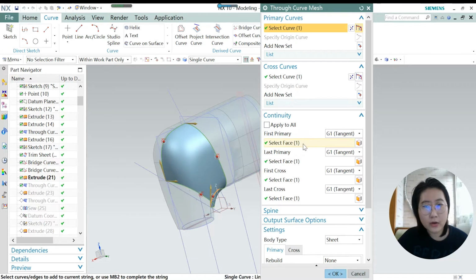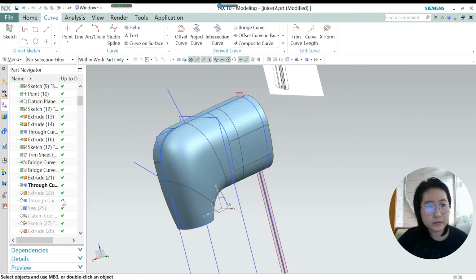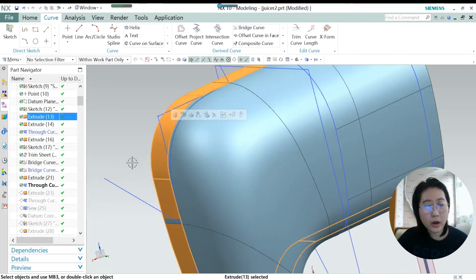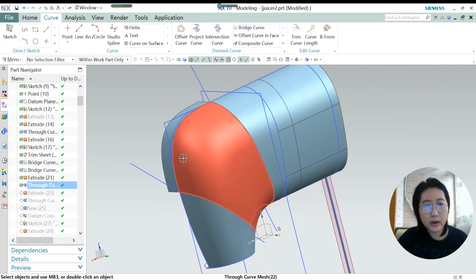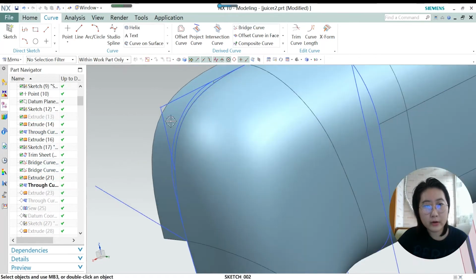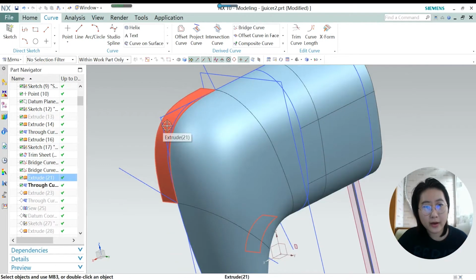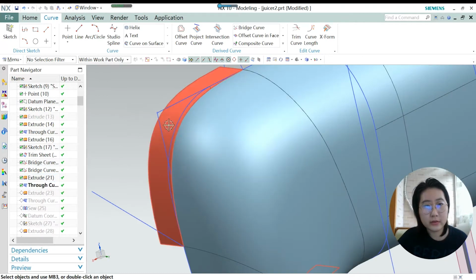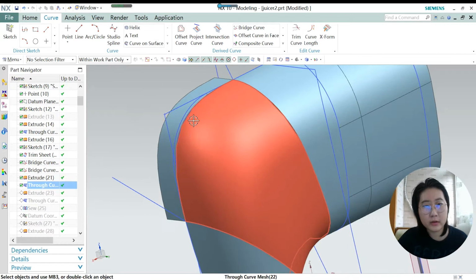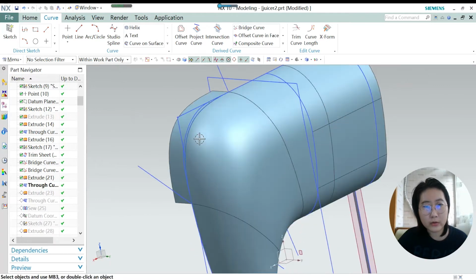Each of the surfaces needs to be tangent with the surrounding surface I created before. So I'm gonna hide this by clicking Control plus B, and it just makes it very clear to you. Otherwise, you're gonna have the question why the surfaces cannot connect to each other very well. So in this view, you could see this surface and this surface are very smooth between each other.